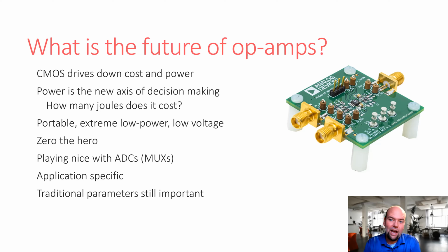If you're a device that's feeding a signal to an ADC, what you're seeing is something strange. You're seeing basically a very high impedance load, but occasionally, like 10,000 or 100,000 times a second, this thing is a very capacitive load. So it's this one microfarad or 0.1 microfarad capacitor or whatever they use to actually sample the signal, and that's strange, and that can lead to unusual, unexpected behavior in the output of an op-amp. So a lot of op-amps now are sold and geared towards being multiplexed for an ADC for a digital system.